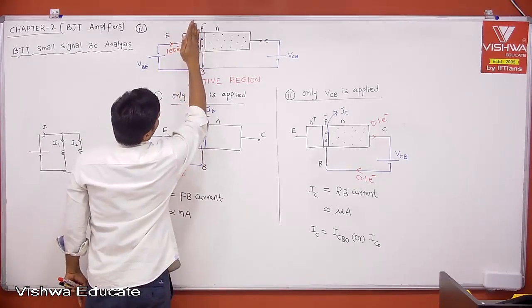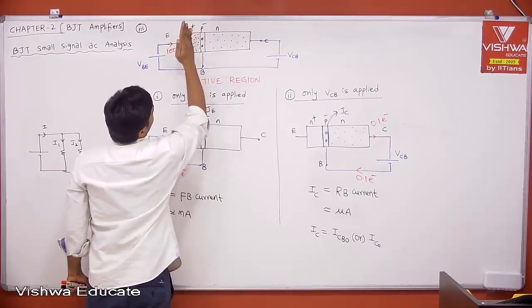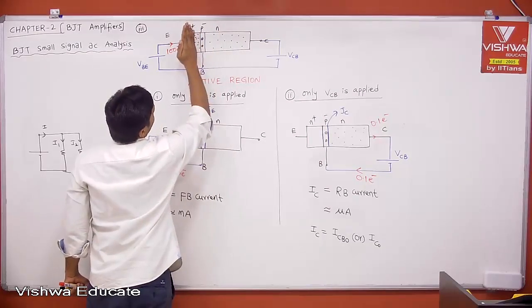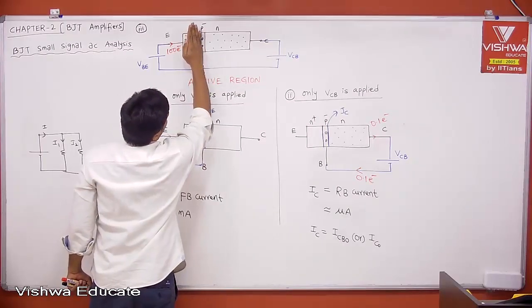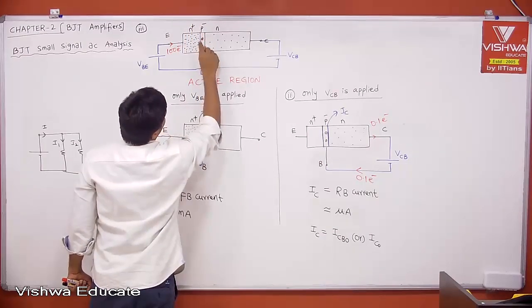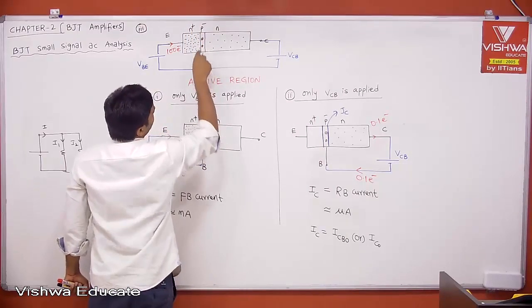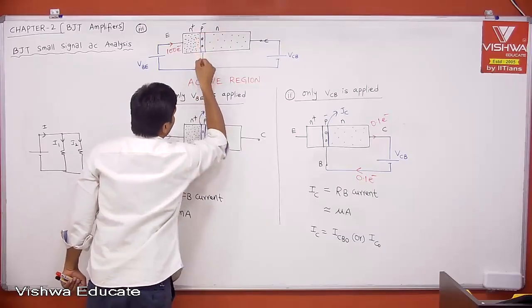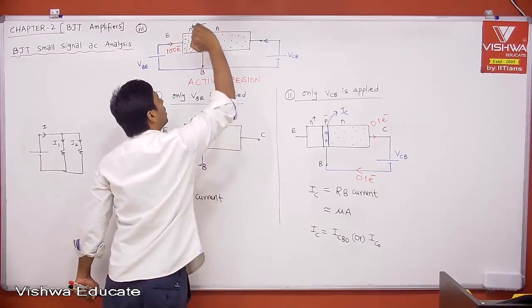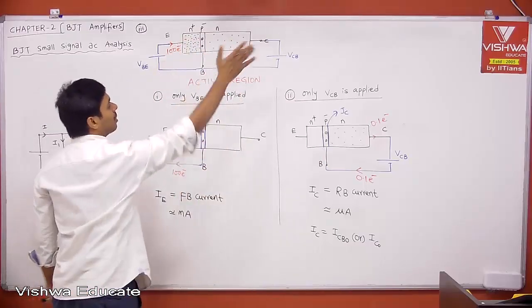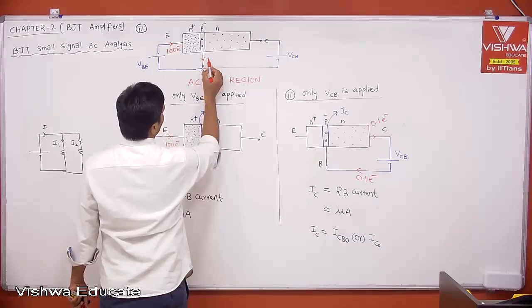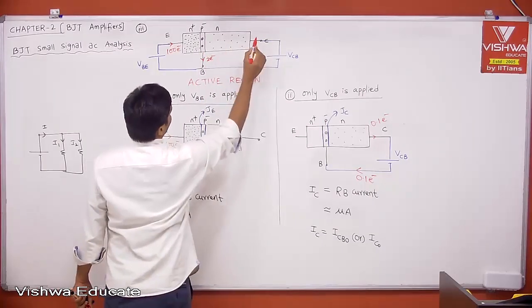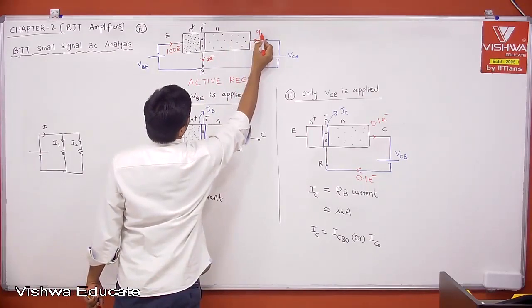When they are entering, there is something called diffusion current. Therefore, when the diffusion current is present, they travel only a little distance, which is the reason why the base width is very small. When they enter the base, they travel only a small distance while traveling from emitter to collector. Because we have few vacant states, which are nothing but holes, only a few electrons will come out of the base. Almost all electrons entering the collector will come out of the collector. Let us say, again as an example, 2 electrons are coming out of the base and the remaining almost 98 electrons are coming out of the collector.